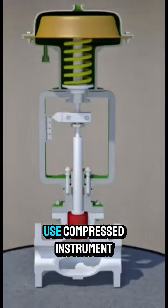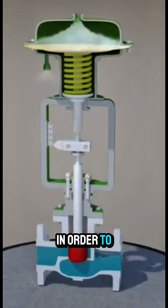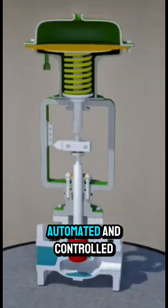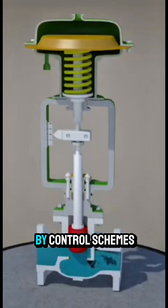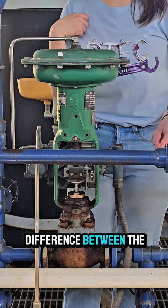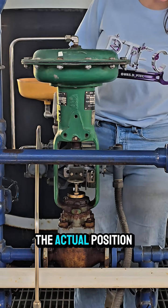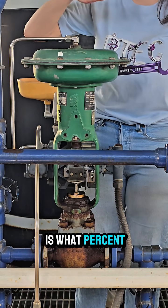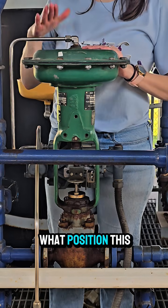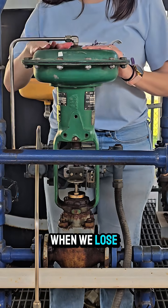Pneumatic control valves use compressed instrument air to adjust the valve position in order to control one of the process variables in the unit. The valve is automated and controlled by control schemes and the process board operator. It's important to keep in mind the difference between the valve position and the actual position. The actual position is what percent open the valve actually is in that moment. Valve position is what position this valve will end up in when we lose instrument air.